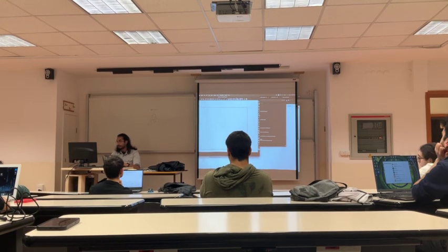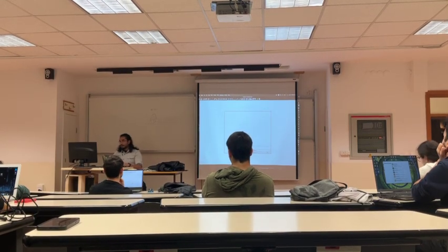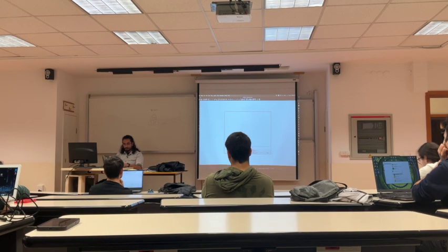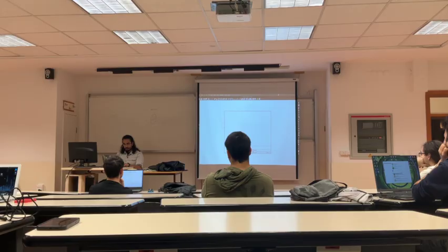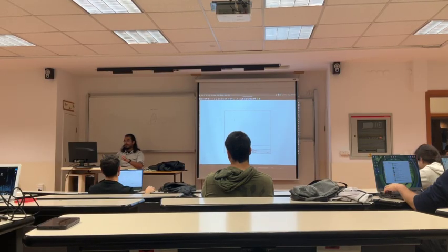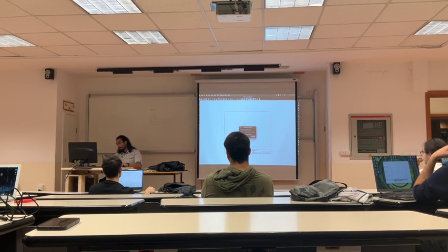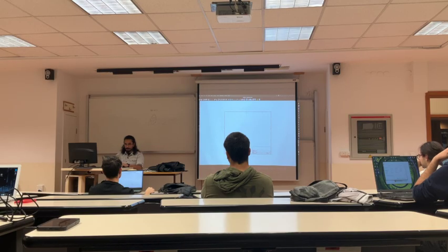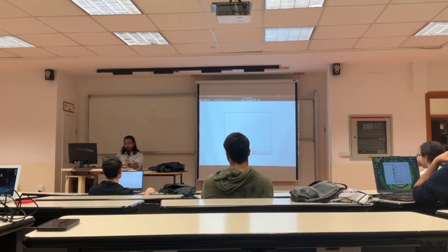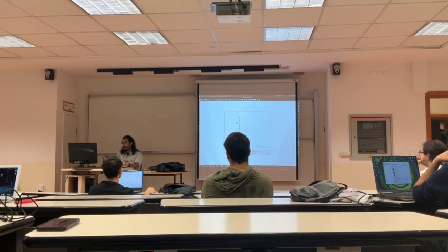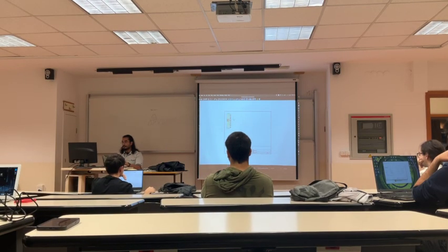So here is the schematic. And we are going to start the schematic. So I click here at components, or I can click A directly. I type USB Type C, and I click on USB-C receptacle. This is the first thing that I'm going to add on my PCB. We generally add the important components first, and then we add the resistors and the other components.